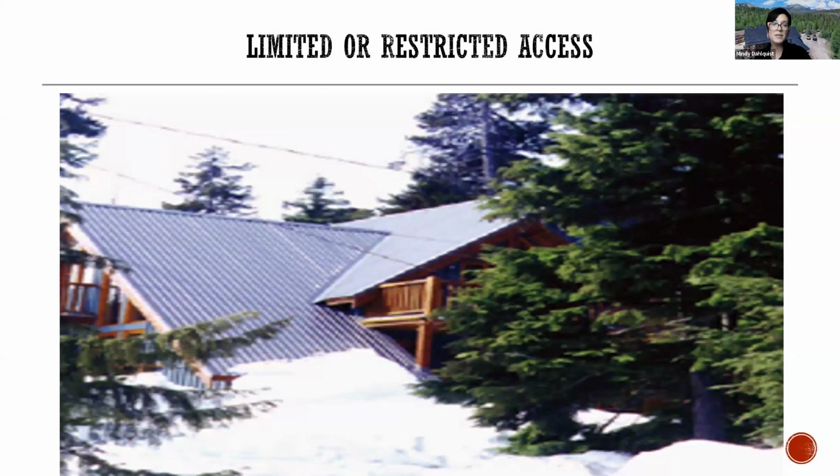Many homes and cabins, and also commercial structures, are built with snow shed in mind. When that is happening, you do have to take a lot of precaution on where that snow is going to go. So this cabin was built with snow shed in mind. They're allowing that snow to come off of the roof surface, but the biggest problem is the entrances to this cabin. The parking is down on the far left of the photo, and there's a beautiful walkway that takes you to the main entrance that is on the right behind that pine tree over there. So hopefully they have a nice little snowmobile to get them and their groceries to that front door, because otherwise that's going to be quite a task.